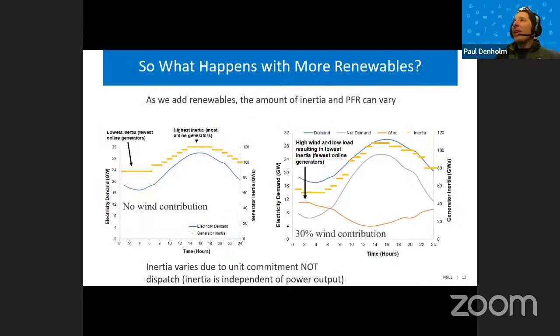So we really have historically not talked about frequency response in the power grid for the first 100 years. It's just something that we design around and nobody worried about. Nobody talked about inertia 20 years ago, but now we talk about inertia quite a bit. And the reason is because wind and solar photovoltaics do not inherently provide inertia or primary frequency response. If you just put a standard old wind turbine or a standard old PV system on the grid, it provides neither real physical inertia, nor does it inherently provide primary frequency response, because they don't have traditional governors.